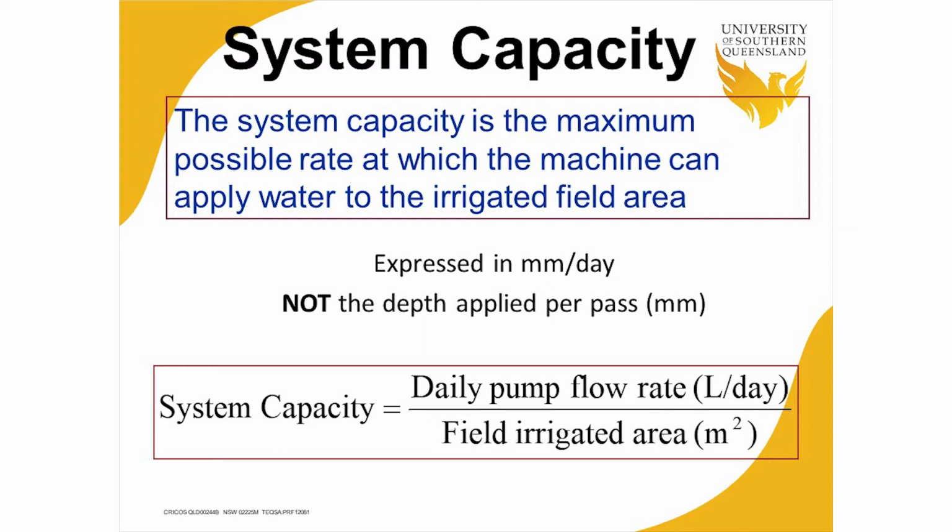Well, one of the things that's historically occurred with centre pivot systems in Australia has been the system capacity has been woefully designed. And what we've tended to have happen over the decades has been a very strong impact of poor performance of things like centre pivots because the system capacity was not good enough. Particularly a case where people are focused around full irrigation capability.